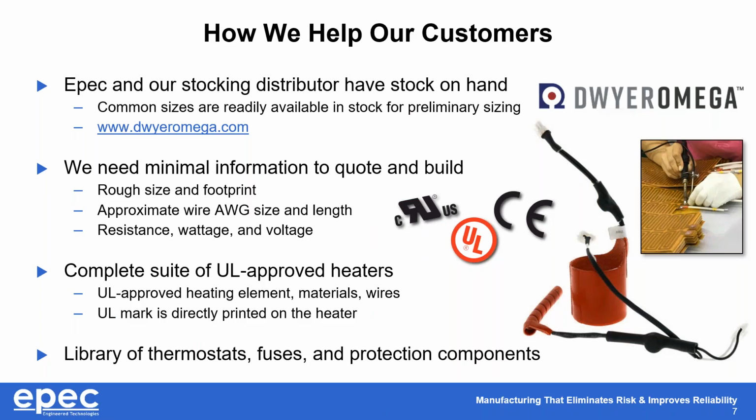We don't really need a lot of information to start the process and get you and your team a quote, but we do need the rough size and the footprint of the heater. We'll need to know how you're energizing it, what the wire gauge and length would be, and lastly, how you want the heater to perform. Since these are fixed resistance heaters, if you know the open circuit resistance of the heater, that is what we need. But then we can do further analysis to make sure that it won't operate too hot with the supply voltage. For that fixed resistance, we typically guarantee about plus or minus 10% of whatever nominal resistance value you're targeting.